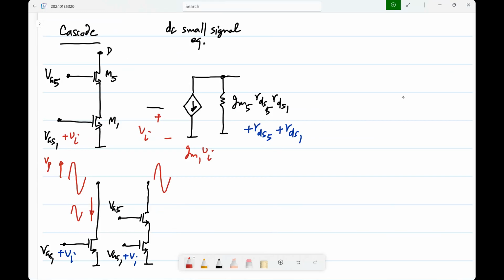So you can see that the signal, if you have Vp over there, it is approximately attenuated by Vp times GDS5 by GM5. Okay. So roughly speaking, it's like having RDS5 from there to there and GM5 from there to ground.